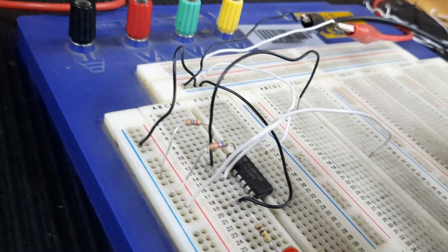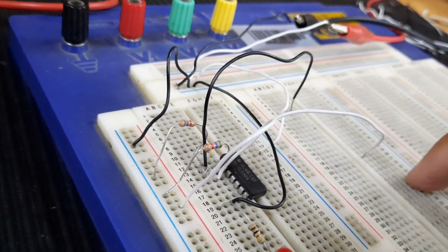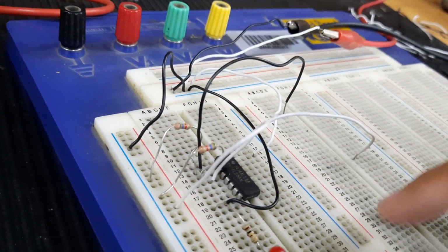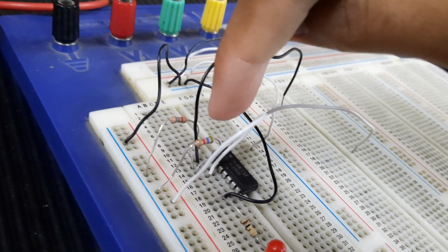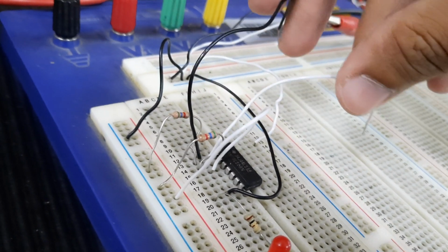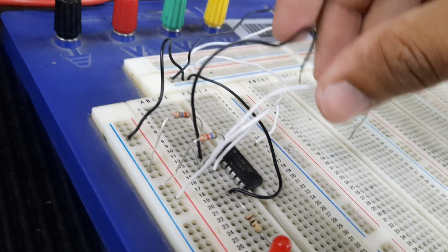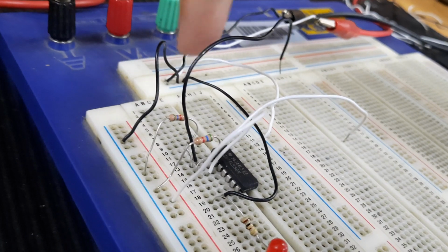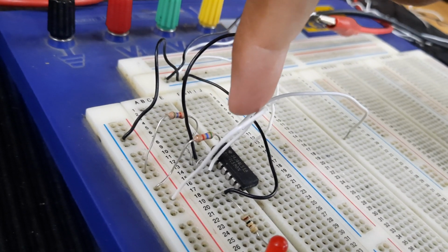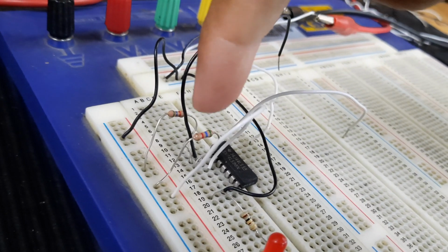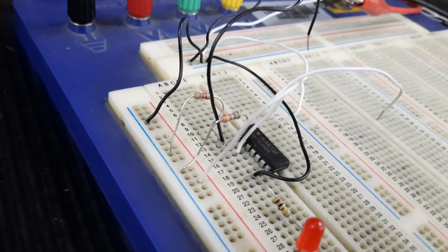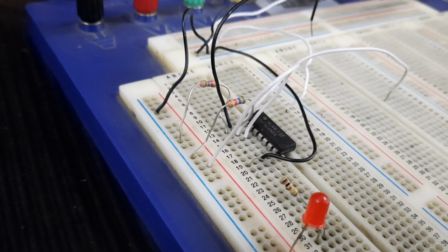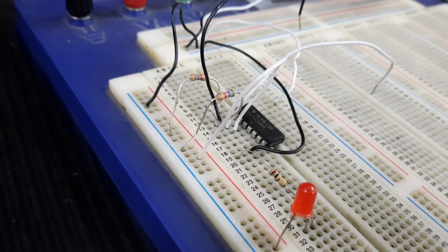If you want your input pin to be on high voltage or 5 volts when you are not giving the input, then you need a pull up resistor. So if no input voltage is coming on the input, 5 volts should come through this resistor, which in this case is 0 volts because it is a pull down resistor. It is a good practice while making combinational circuits or any digital electronic circuit, or whenever you are using a gate.